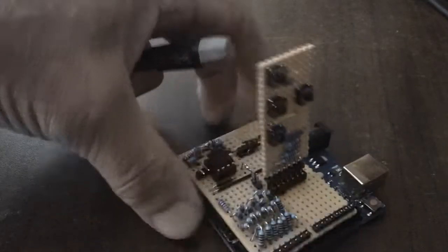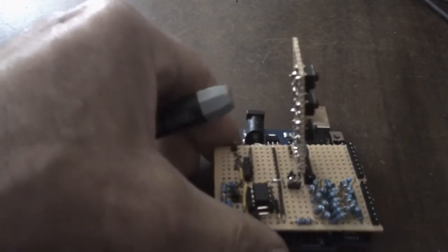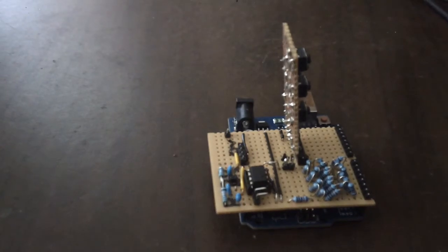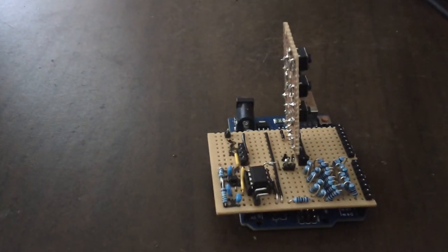Let's have a look at it in a bit more depth. There we go. There's a few supporting components, not very many, but I have put in quite a lot of decoupling, which is quite important. Because we don't want lots of noise getting into the op-amp, because it would rather defeat the object really. So that's pretty much all it is. It took me a couple of hours to make. In fact, it took me more time to go down through a bandolier of about 1,000 resistors than it took me to actually build the rest of it.